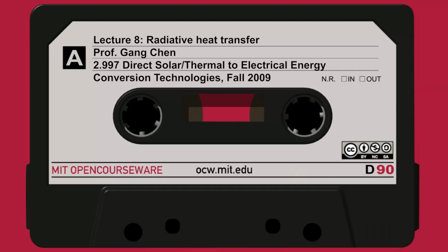Let's say now if you integrate all reflected intensity, you get the directional spectral reflectivity. When I say directional spectral, that's coming in and integrating over all angles. So when I do bidirectional, notation-wise, I have a double prime. And when I integrate all angles of reflection, I get directional spectral. So this direction only means incoming, because I integrate the reflection over all angles already.